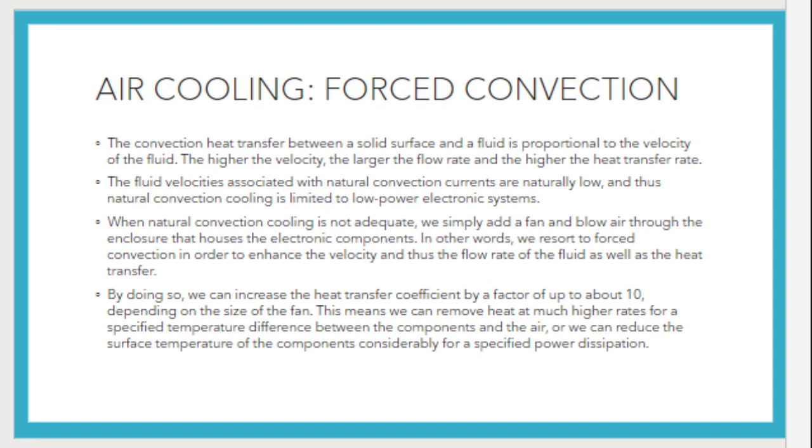In other words, we resort to forced convection in order to enhance the velocity and thus the flow rate of the fluid as well as the heat transfer. By doing so, we can increase the heat transfer coefficient by a factor of up to about 10 depending upon the size of the fan. This means that we can remove heat at much higher rates for a specified temperature difference between the components and the air, or we can reduce the surface temperature of the components considerably for a specified power dissipation.